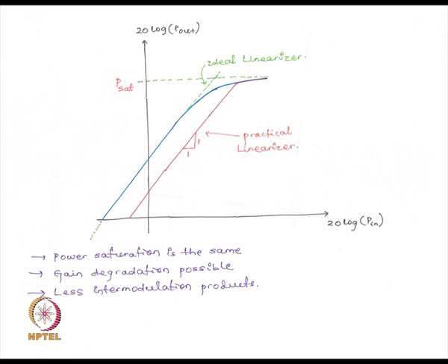One other thing is that what happens during combining is that the overall linearity of the transistor, or the IP3 of the transistor, is not improved, but just that the curve is shifted a bit. So, if initially this blue curve was representing the transistor's input-output characteristics, now due to this power combining, the entire characteristics shift rightwards, and so the input power at which the saturation or gain reduction starts happening is now shifted to a higher value, and that's why we are getting that higher value of gain.